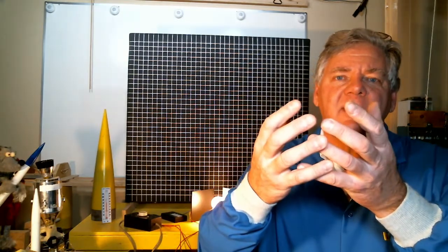The first heat transfer concept I want to talk about is convection. What do I mean by convection? That's when a fluid, such as air, is heated by some sort of heat source, and as it's heated, it becomes less dense. When it becomes less dense, it becomes buoyant and will want to rise. That leaves a void where that air used to be, and cold air comes in behind it to fill that void, and it in turn becomes heated, and it also rises.